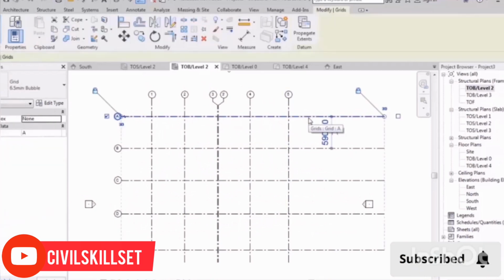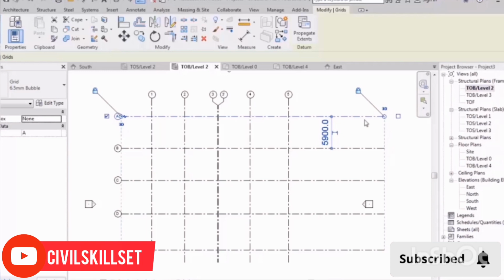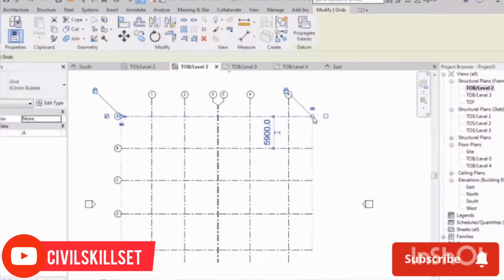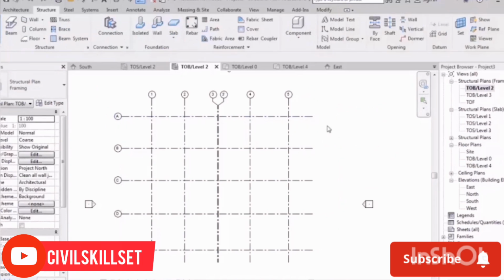The next point is about this: if you select your grids, you might see a lock and then you might see a 3D here. I want to tell you what these are, right? I've already talked about this subject in the levels. Let's just have a review. If it's locked, when you move one of these grids, all of them are moved, just like you can see. If you unlock it, just that grid will be moved. This is what it is about the lock.